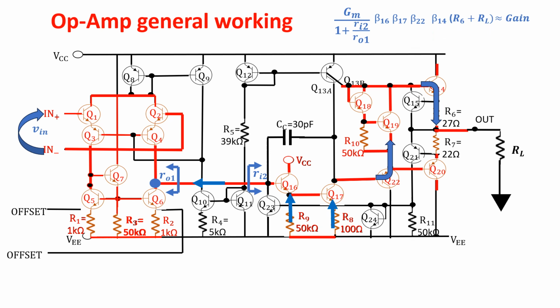So this is the gain for this kind of 3 stages OpAmp, and you see that even if you lose something because of the finite first stage output resistance, nevertheless the gain is very large because of the product of betas. In the end, the OpAmp converts the input voltage into a current driving the base of the second stage, where this current is multiplied by the betas of the Q16, Q17 and Q22 and supplied to the load. Of course, in the case of the uA741, all the assumptions we have done aren't true, so we also lose gain because the Darlington is not perfect and because of the emitter followers in the output stages, but we'll see later the gain is still high.